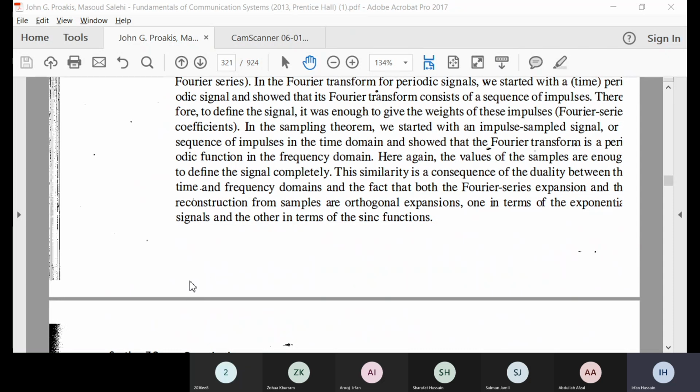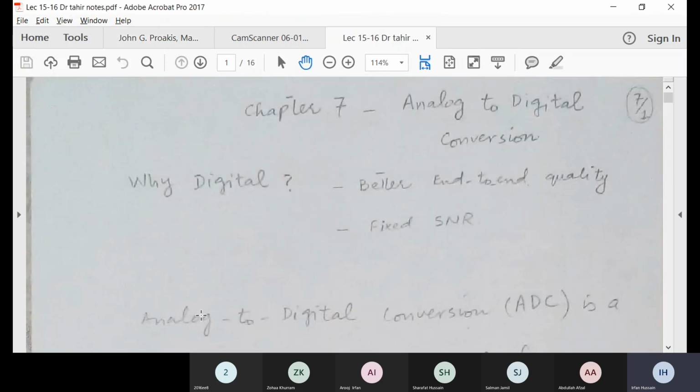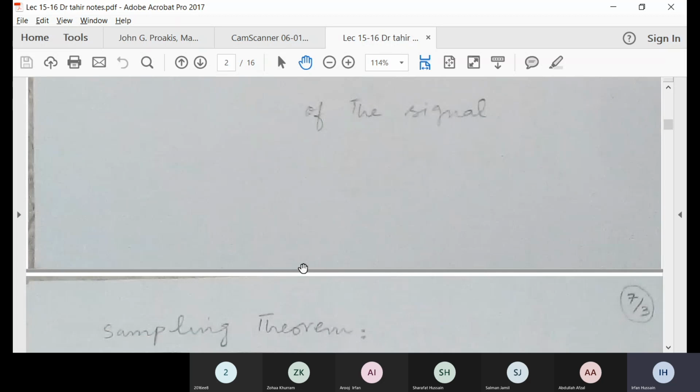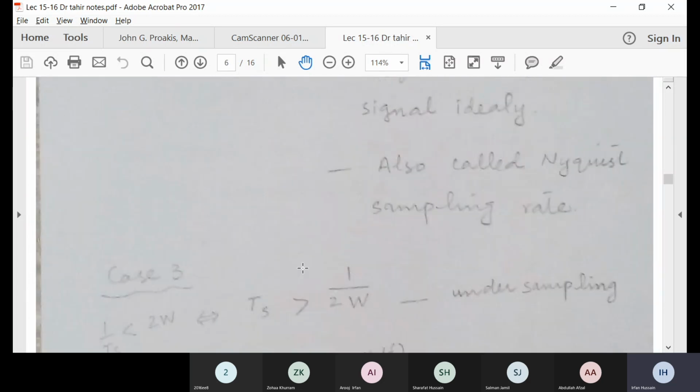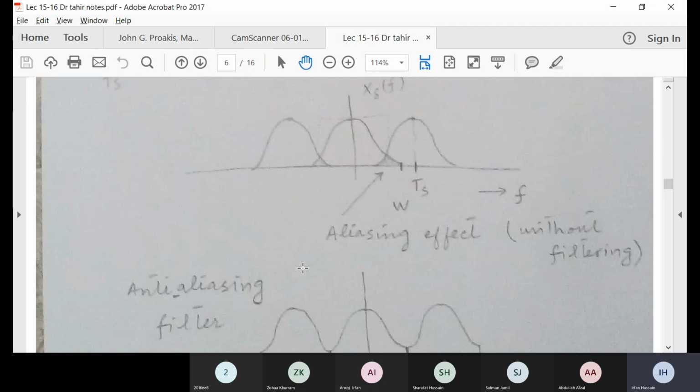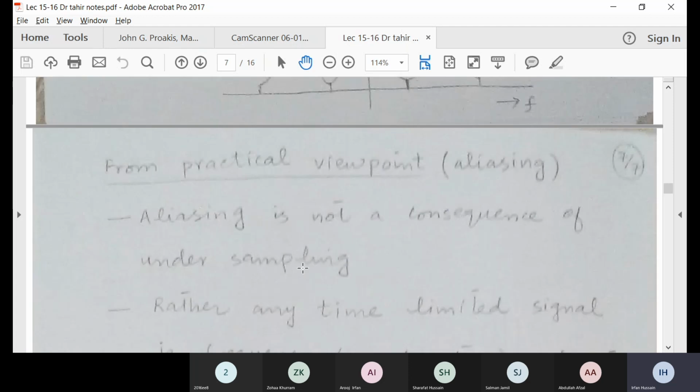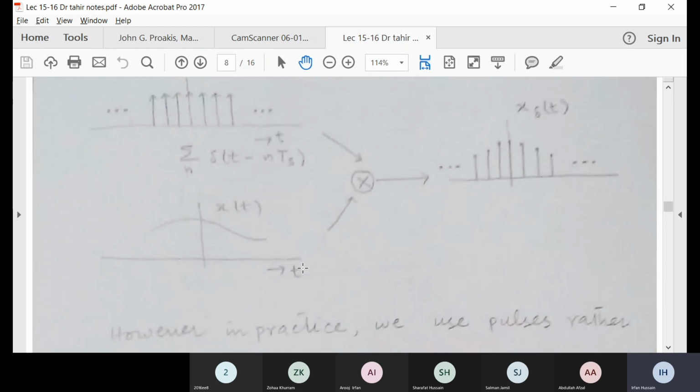in the book. And so first I discussed that we need an anti-aliasing filter or a sampling filter. So first of all, to make sure that the signals are restricted to a bandwidth, so that when you are sampling at double that bandwidth, there is no aliasing, all of that.